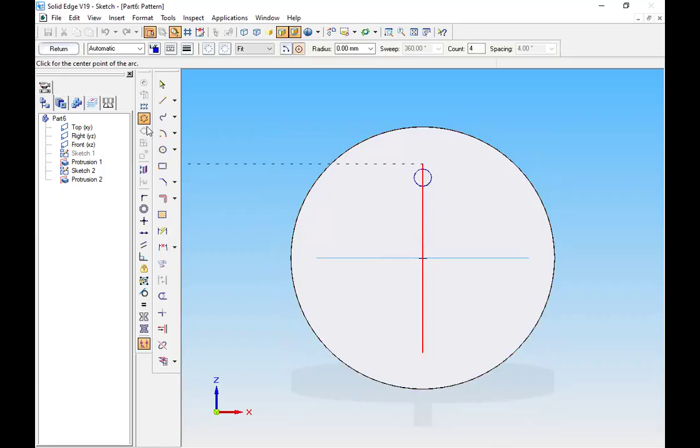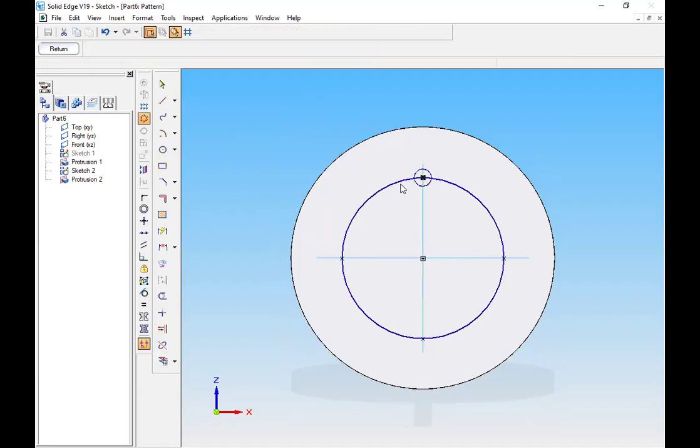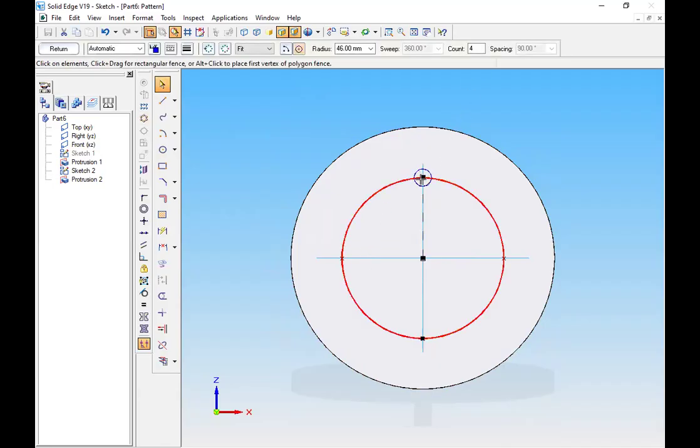Okay. So once you take up this, make sure you have taken a circular pattern. Radius, so from this center to this center. Next, orientation. From which direction do I have to move? Anti-clockwise or clockwise? You can make out there. An arrow is coming out. I'll click on the arrow here. Number of count: by default it will be 4. See, 1, 2, 3, 4. Instead of 4, I'll give some 30. Return.